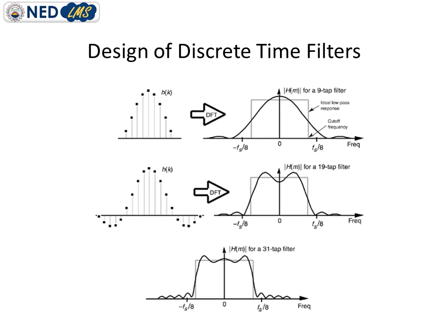You can notice it from the second figure. In this figure we have taken the side lobes also, in other words I am utilizing these samples to extract the filter coefficients, and then these filter coefficients will help me in designing the difference equation, and that difference equation is actually my FIR filter.